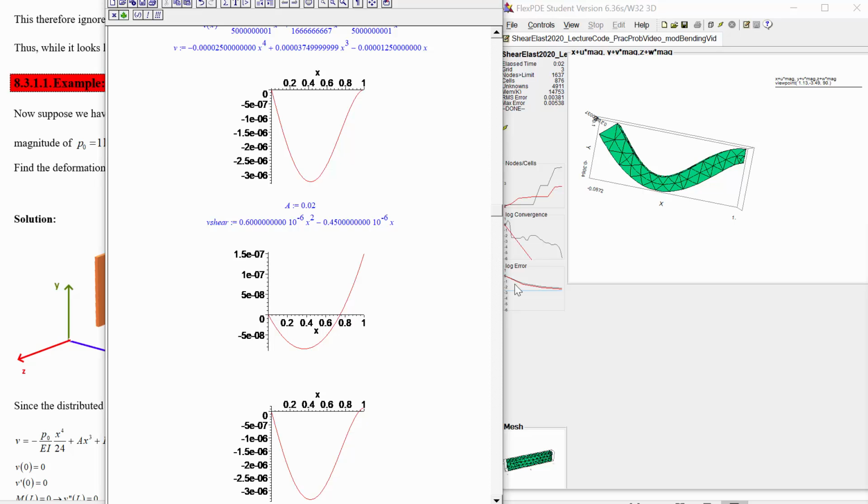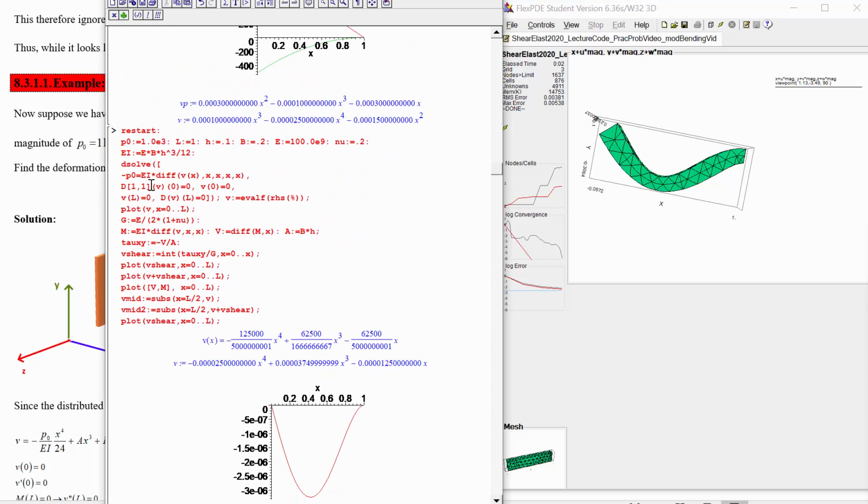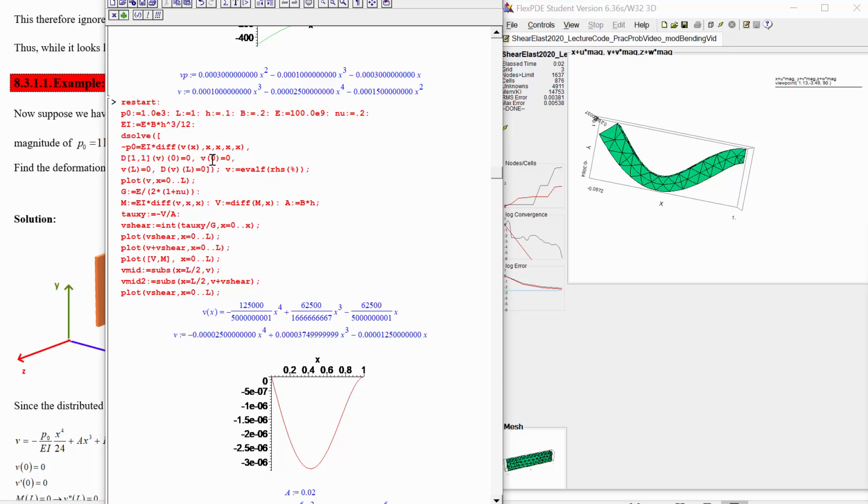We are only able to apply one boundary condition in shear because it's just a first order differential equation by itself. So really, we should be building up this differential equation to account for shear and bending together from the start, rather than just doing this fourth order one in bending displacement alone and then adding the shear displacement later.